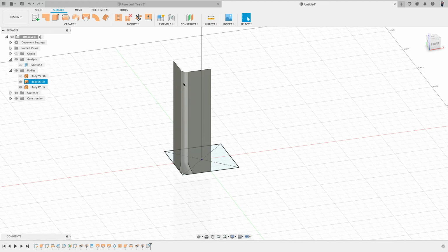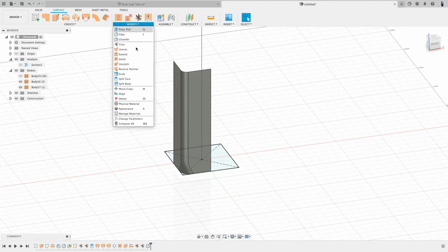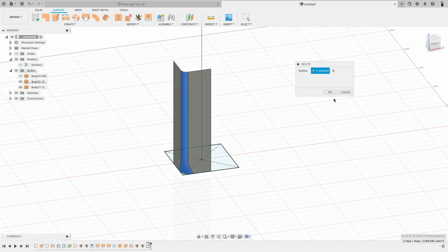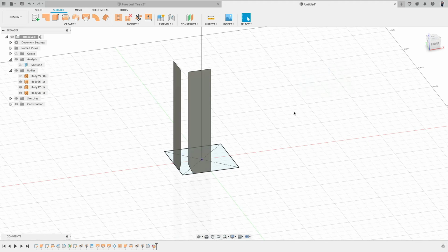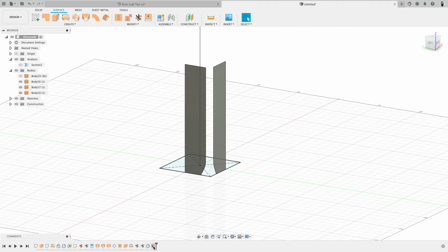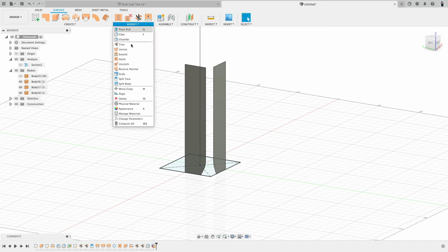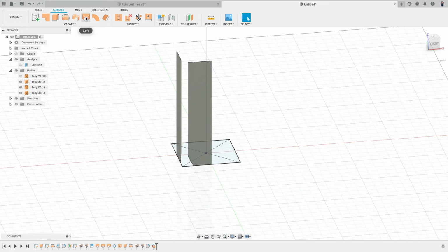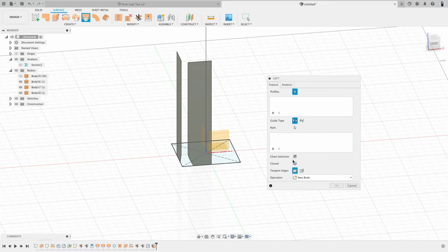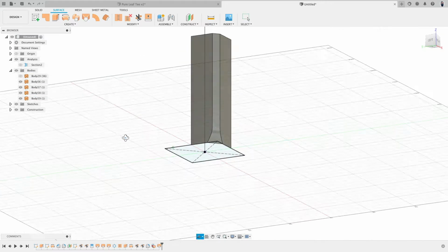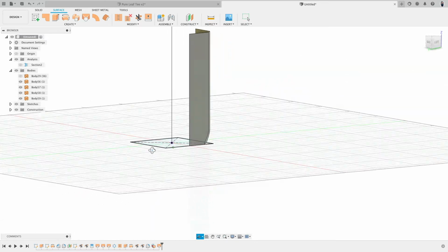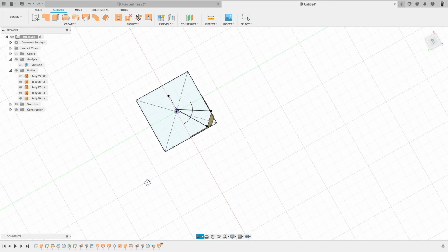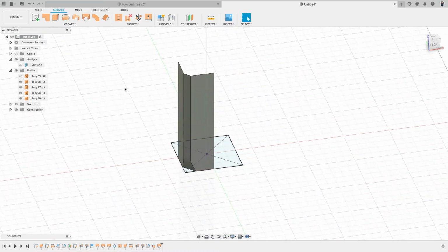We use the fillet like a chamfer, and now we go ahead and we delete actually this face. There. See, there's the delete command. Again, I did not delete the modeling, I just deleted it. And now I can go ahead and say loft. This is turned off. And loft this. Straight. You see, really nice. So it looks like a chamfer, but it flows.